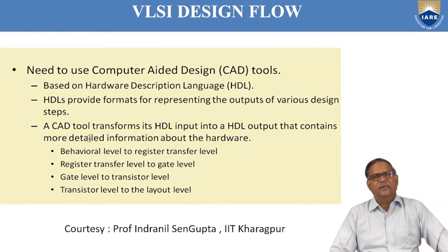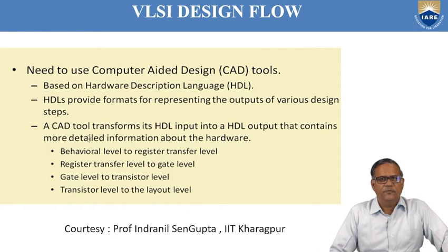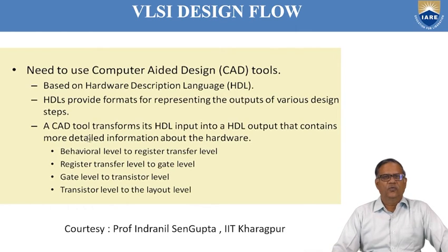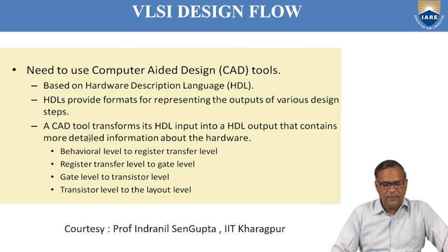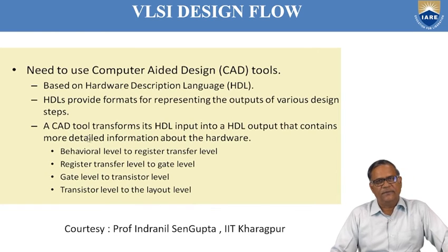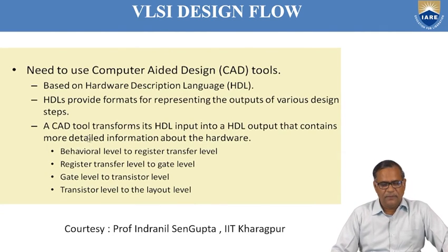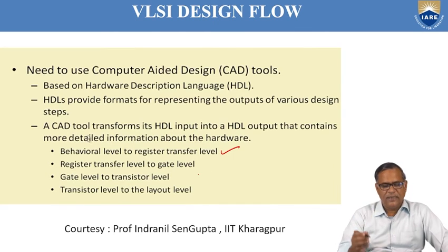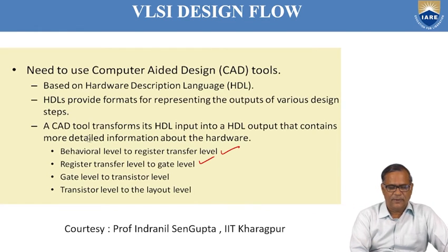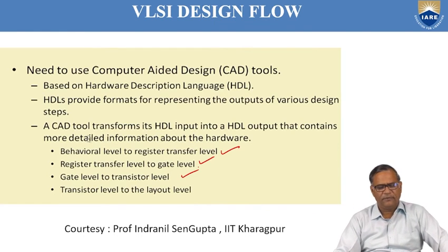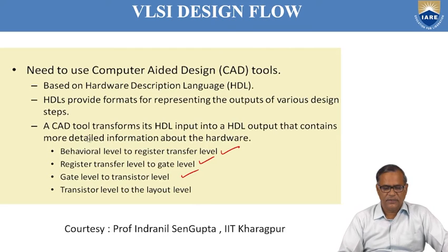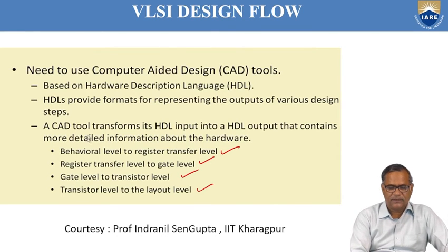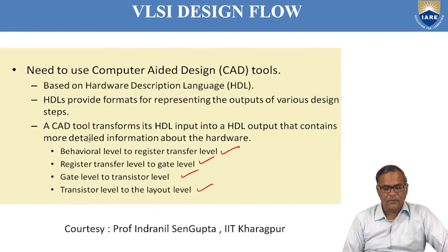A CAD tool basically transforms the HDL input to HDL output, which contains more detailed information about the hardware. So first is the behavioral level to register transfer level, then from RTL level to gate level, then from gate level to transistor level, then from transistor level to layout level. These are the steps of the VLSI design flow.